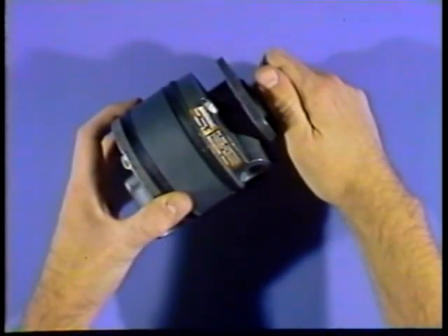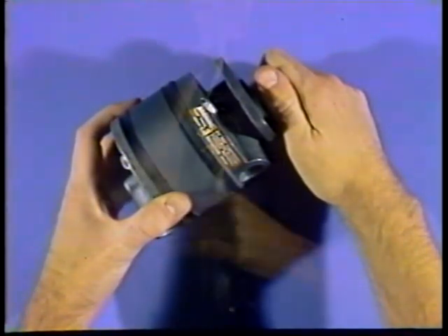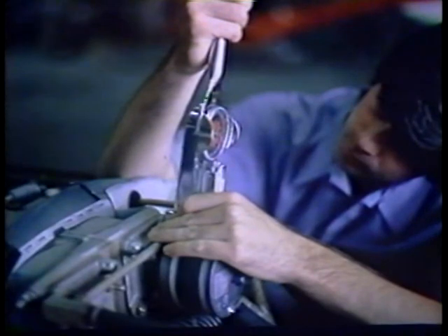Prior to installing the pump in the engine, determine if the pump will turn without binding or in a lumpy manner. Now, using a new gasket, install the pump on the drive pad, mounting it in the position that provides best clearance for the attached lines. Using the proper washers, lock washers, and nuts, torque the attached nuts uniformly from 40 to 50 inch-pounds.